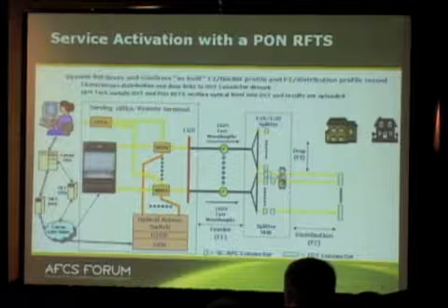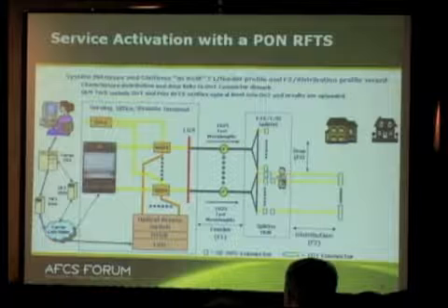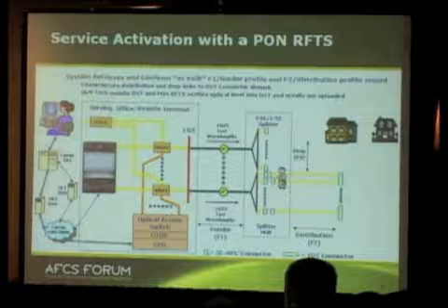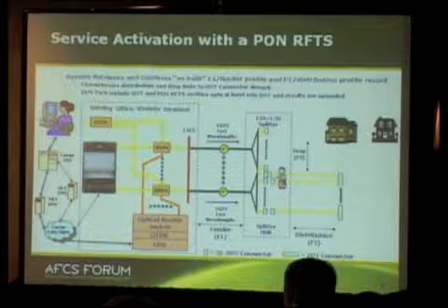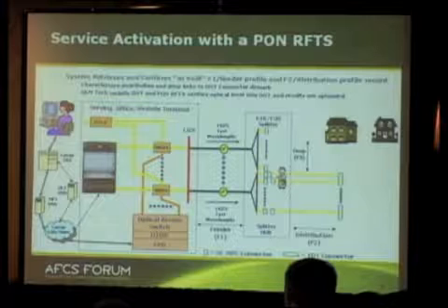In other words, the fiber's good up to that connection where that FTT is going to be. In this case, he's going to install an FTT as such because it's the first one at that location. Normally, say that fiber was bad, he would run out, check for lights. Gee, I can't see light. Run back and forth and stuff like that. And that can be,